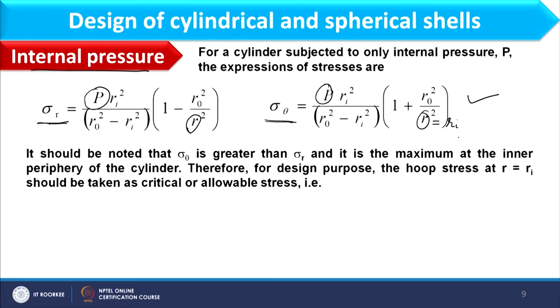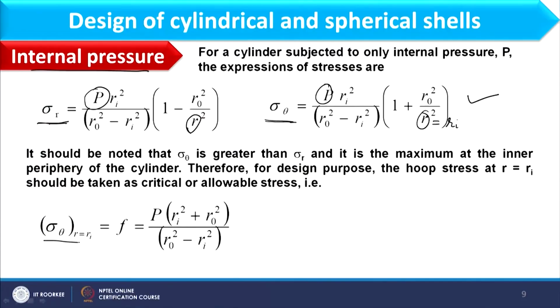Here I have to maximize the stress which can be generated in the system. Okay. So, sigma theta would be maximum when r equal to Ri, and that would be the maximum possible stress in the system, and that stress we can replace with the allowable stress value, because at that value we will design the system.